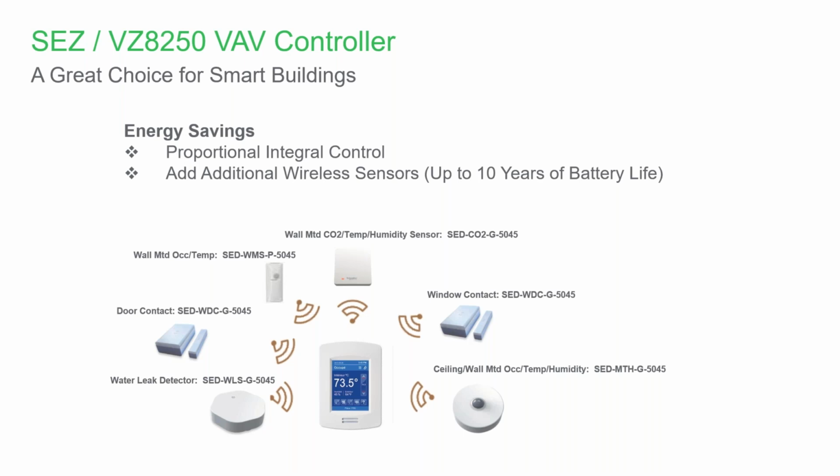With the addition of these occupancy/temperature sensors, you can put them in the other rooms and make that value report back to the room controller here. And if it's occupied, then use that temperature for every room that's occupied. And you can select the highest, the lowest, the average, whatever you'd want to do. And we'll talk about how you do that here in a little bit.